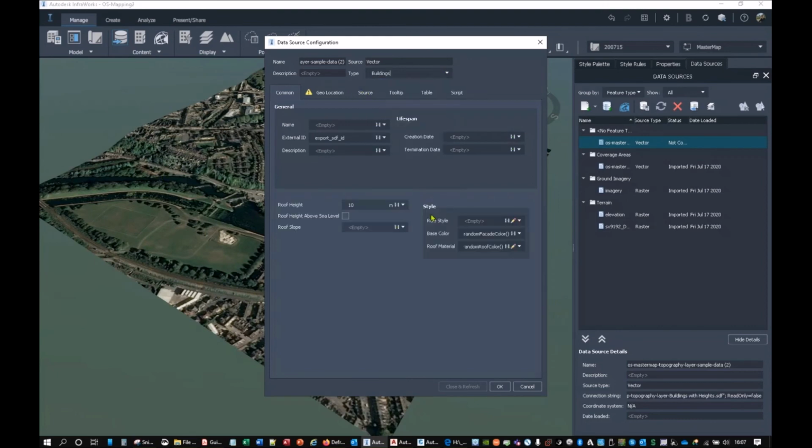So go in here, they are buildings. Instead of putting a 10-meter building height on it, I'm going to use that data table that you saw in AutoCAD Map 3D, and I've got one there called Relative H2. Basically, they've got maximum height and relative height. Maximum height is from 0, so it might be 30 meters above sea level, and relative height is from the base of the building, so it might be 10 meters. Then you've got H2, which is basically the average eaves height, as opposed to max, which will be the top.